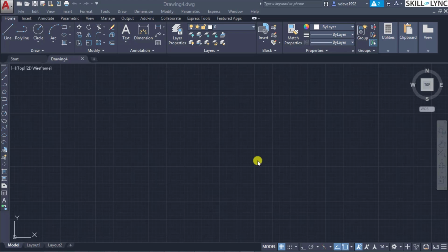For example, if you're plotting an assembly drawing that consists of n number of parts, you can insert a table to indicate which part is what. You can also use annotation for dimensioning and tolerancing, and for hatches, callouts and blocks. These are the typical annotations that we use, and for the fundamental of it, that is to give notes to the drawing, we use text and MText. So let's look into the first option, text.